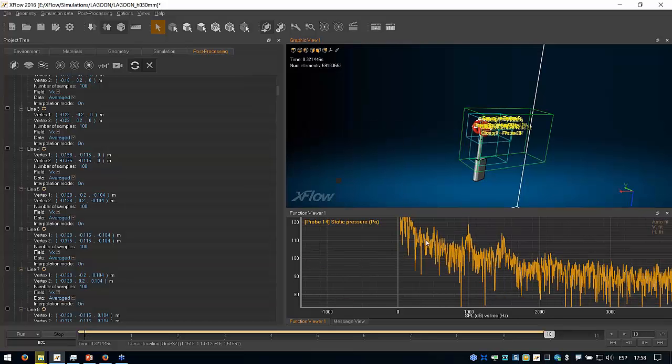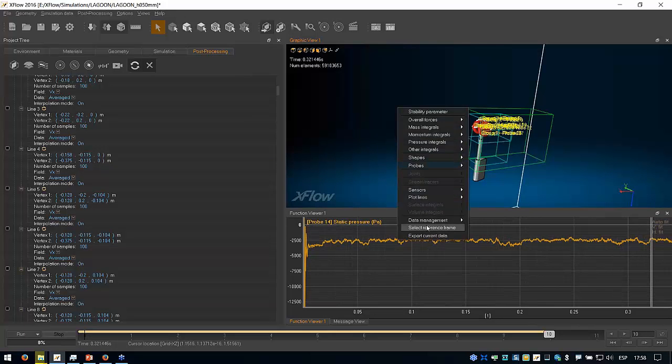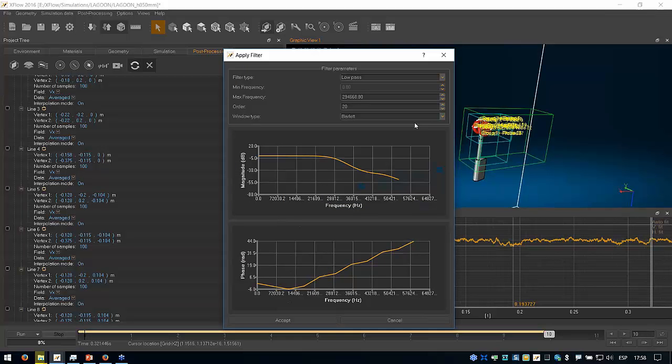So apart from that, we've got a couple of different options that allow you, for example, to apply a filter to the signal. So you could just filter the signal before processing it. If I want, I can have a low pass, band stop, or high pass filter. I could say I want to check my signal between 800 and 1200 Hertz, for example, which is in between the resonance frequencies. I could determine the given window type.